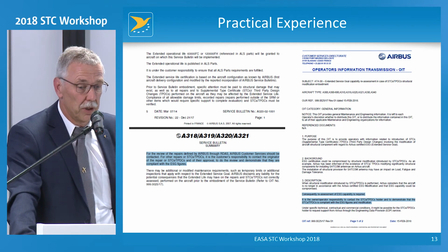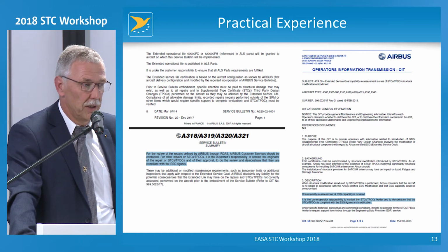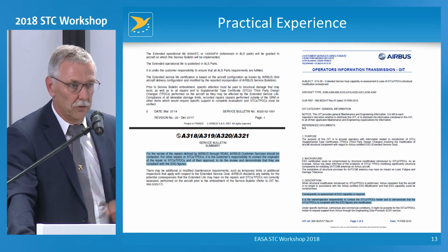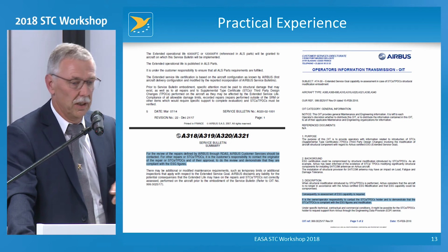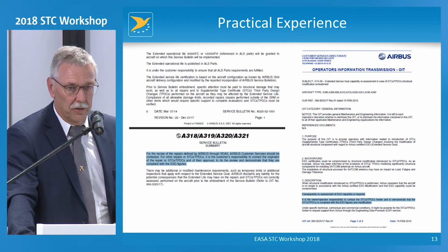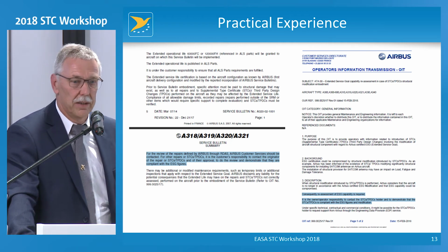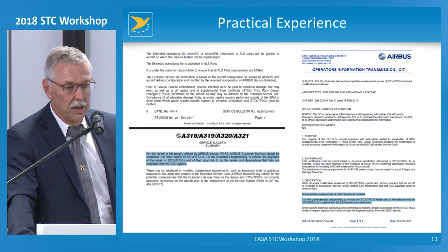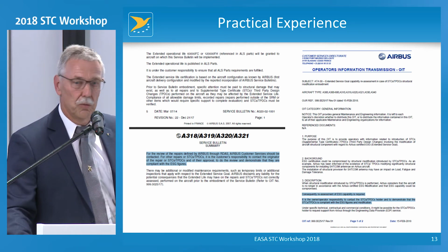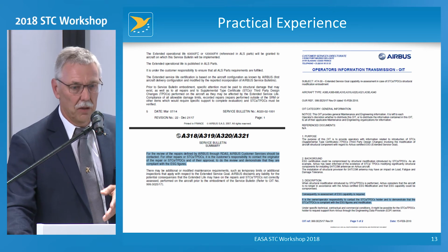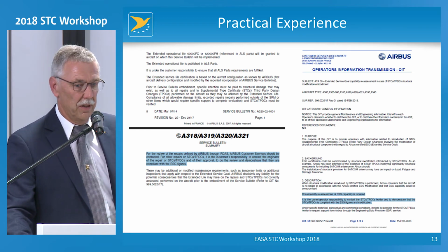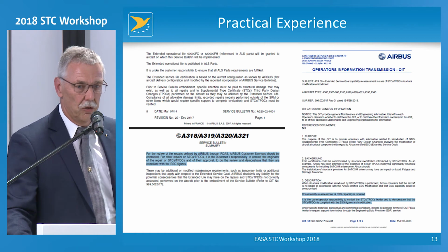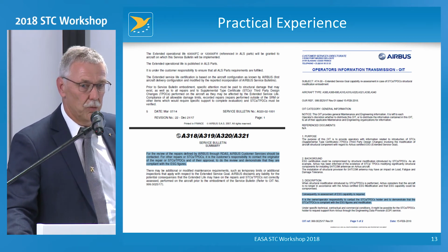So that is something that was worded in a different way before. Airbus initially had a wording there that pointed to the STC holder that they are responsible for recertifying their STCs, and this was questioned by the airlines using this aircraft, how this was meant, and we have agreed with Airbus to use the wording like that, so that the operator, when he decides to implement this service bulletin from Airbus, has to contact the STC company, and then they have to decide whether the provisions are already good for ESG or require a change to the ICAs and the ALSs, in which case this would be a major modification.